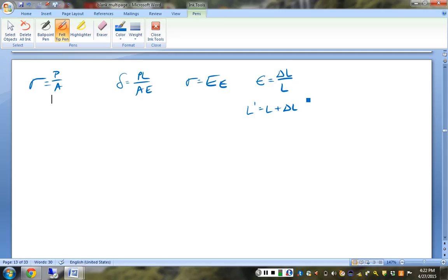What else has got going on? If I pull it this way, how much does it shrink this way? What's that relationship governed by? That's Poisson's ratio, the negative ratio of transverse to axial. How do you remember which way that goes? You know, with your sensible selves, that if you pull on something this way and it gets longer by an inch this way, it is not going to get shorter by 3 inches this way.